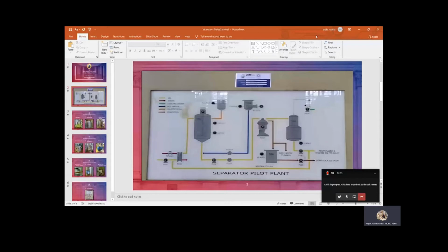Next, the soap stock is collected in the drum and the segregated oil is further processed. The separated oil then flows into a vacuum dryer. The moisture in the oil will be extracted out of the oil. Finally, the oil will be discharged for sampling, to see whether there is a need to repeat the process or not. If the product is as desired, it will be drained out. If not, it will flow back into the neutralizer or washing tank and repeat the whole process again.